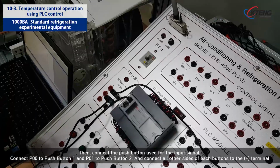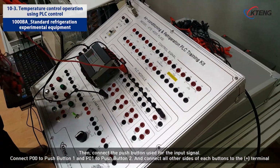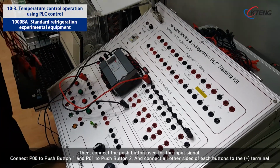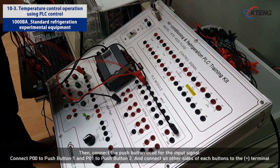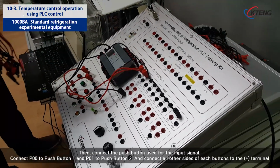Then connect the push button used for the input signal. Connect P00 to push button 1 and P01 to push button 2. And connect all other sides of each button to the positive terminal.